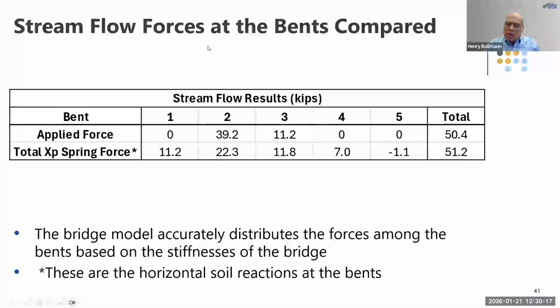But this one on the State Road 105 bridge I was talking about, the 24-inch piles didn't work at this pier. Well, now going back, we see, oh, well, no wonder we're not going to carry this load.